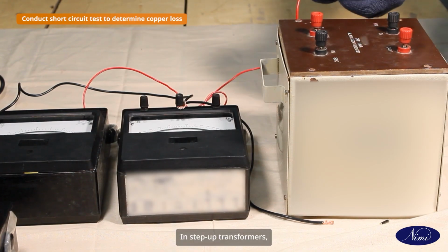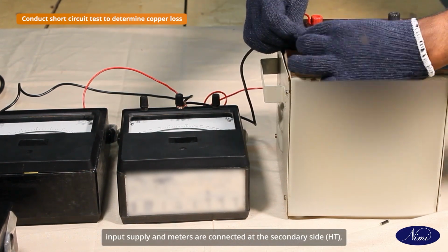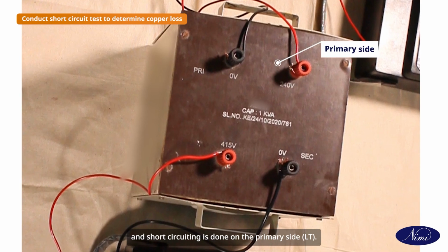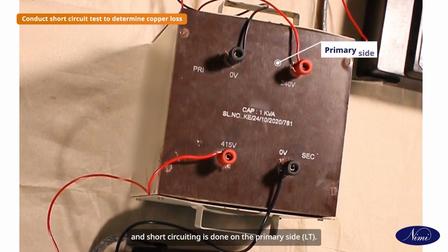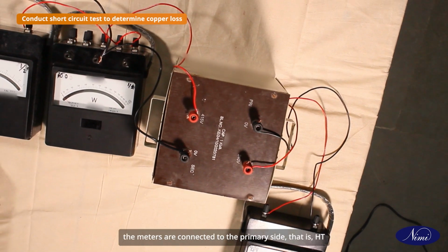In step-up transformers, the input supply and meters are connected at the secondary side, HT, and short circuiting is done on the primary side, LT. In step-down transformers, the input supply and meters are connected to the primary side, that is HT, and short circuiting is done on the secondary side, that is LT.